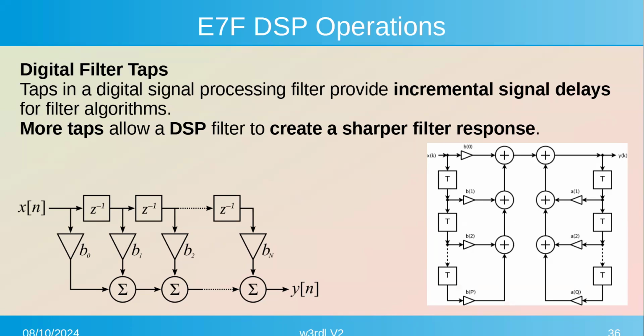A digital filter can actually almost create a perfect square wave type of filter, where you can never get that close with an analog filter. Over here on the right is another infinite impulse response, more typical one, where you've got kind of two recursive loops. Where on the left, it's a standard finite impulse.